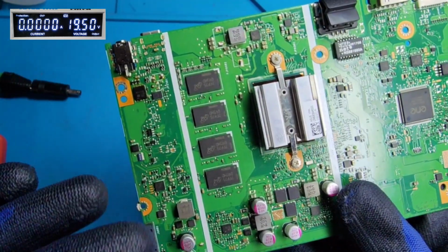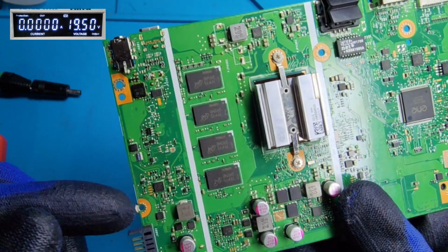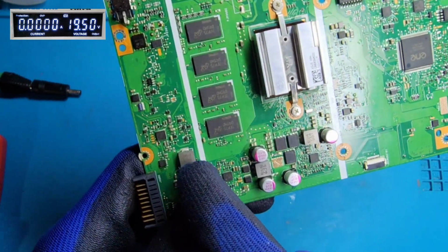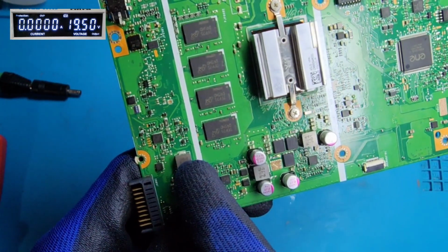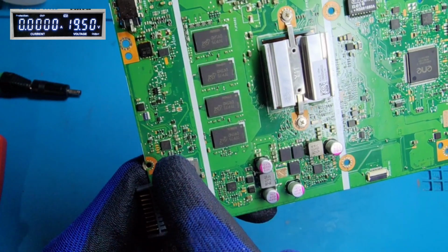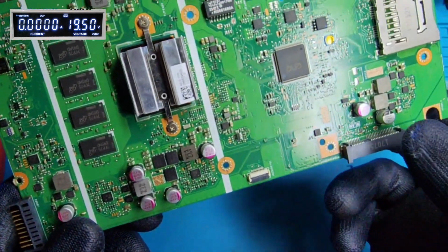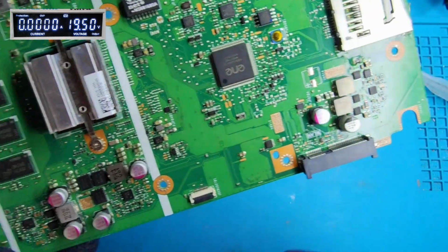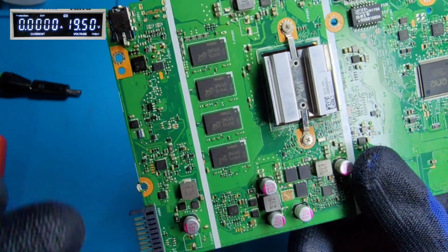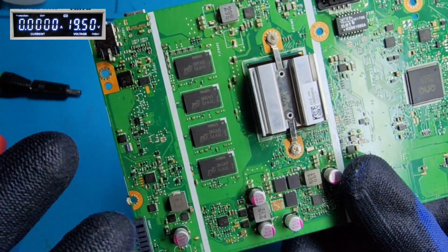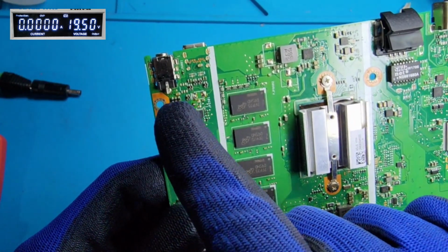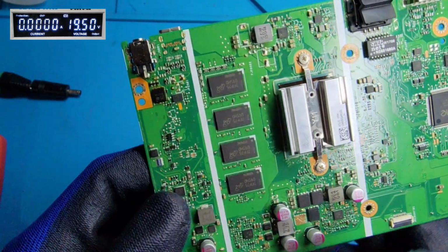You may have noticed when I first connected the adapter, before removing the short on the main power rail and also on the battery section here, the charger IC was not providing the gate voltage, and we didn't find a main power rail on this capacitor here, because the charger IC had detected that there's a short on the main power rail. But if you remove this MOSFET and just short its pins together, what will happen?